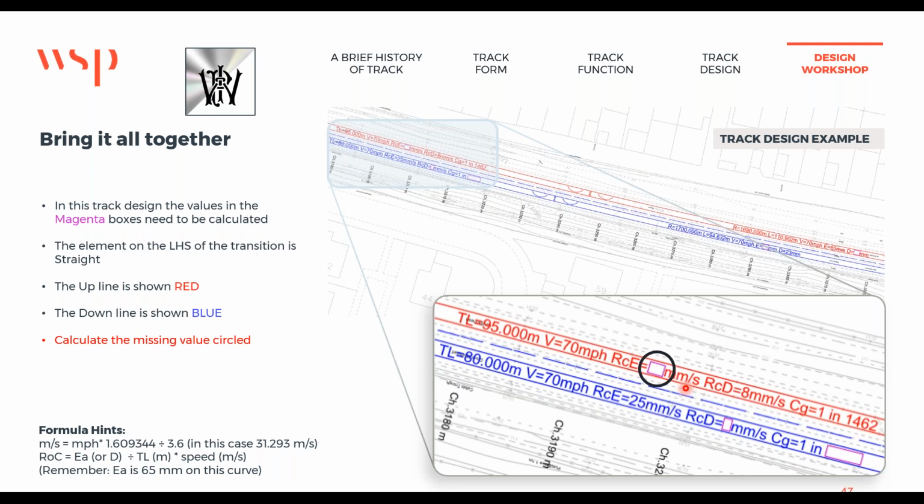And the rate of change is your applied cant, your EA, or your cant deficiency if you're calculating cant deficiency, divided by the transition length. And the TL here, that transition spiral, is 95 meters long, multiplied by the speed in meters per second. So we need to get that down into meters per second. And remember that the EA is 65 millimeters on that curve. Remember, that's up here.